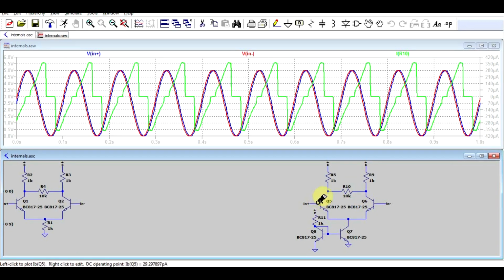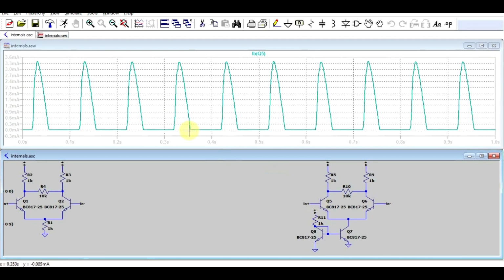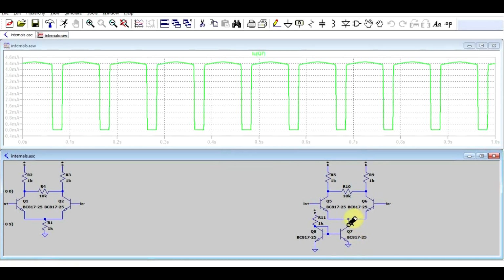When we're driving any sort of OpAmp, we want the input current to be 0. Now if we look at the input current through this stage, we'll see that it's roughly 0 until it's not 0 anymore, until it jumps up to 3 point something milliamps. Now that is completely unacceptable for an OpAmp. So what's going on? Well, our low side current sink has a current threshold of around 4.4 milliamps, which normally is drawn through these upper resistors, either the one on the left or the one on the right, depending on which of the two input voltages is the highest.